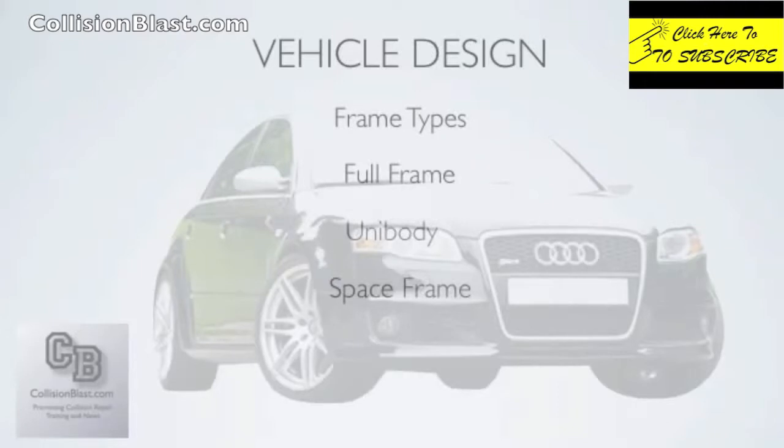Now we're going to talk about a few of the different frames. We've kind of been talking about unibody, but there's actually three basic types of frames, and that's full frame, unibody, and space frame. So let's talk about each one of these a little bit. Now, a full frame, that's just a regular frame like the ladder frame we were talking about, but even those now have crush zones designed in them where they will absorb energy as well.